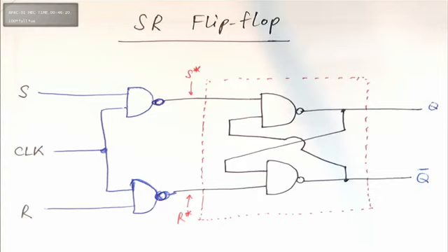You see, in the previous circuit, when you have memory, you need to clock your memory. You can't just ask what is the particular status of this circuit outright like that. You've got to ask what is the status of this circuit at this particular time. So we now have a control input. Clock is used to control when the circuit would take in information, right? When it would log in information, right?